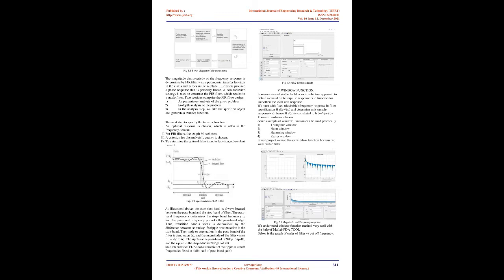FIR filter design. The window approach, such as the Kaiser window method, is used to create FIR filters. To construct FIR filters using the window technique, the fundamental principle is to calculate hd(n) using the inverse Fourier transform based on the ideal desired filter frequency response hd(e^jw). As the formula for hd(n) is infinitely long, to get the unit impulse response h(n), we have to use the window function to meet the requirement. The w(n) is the window function in this case.